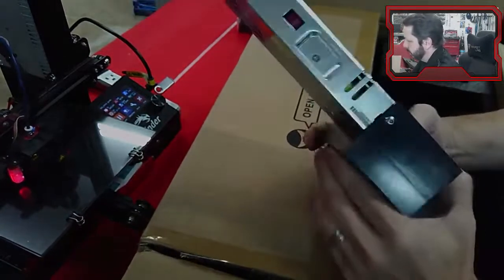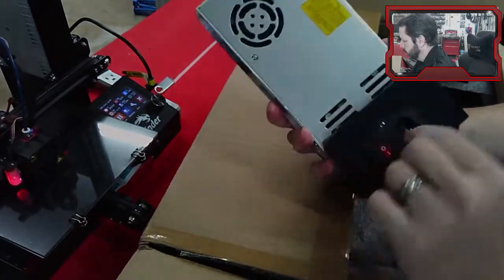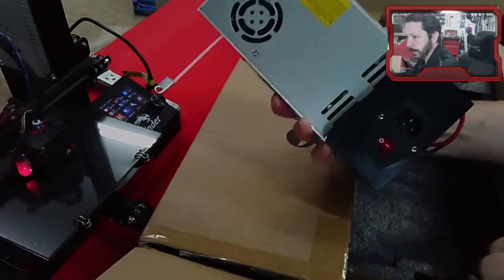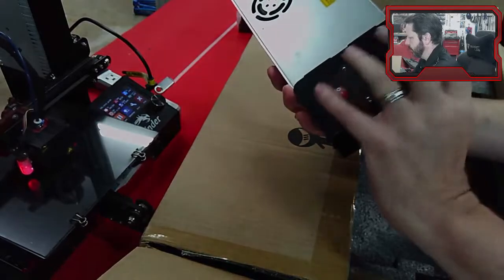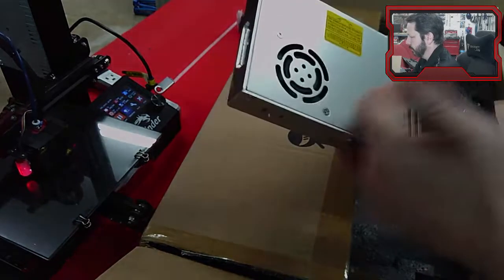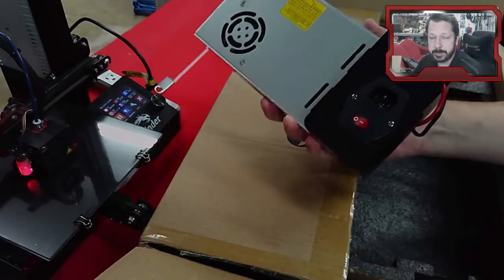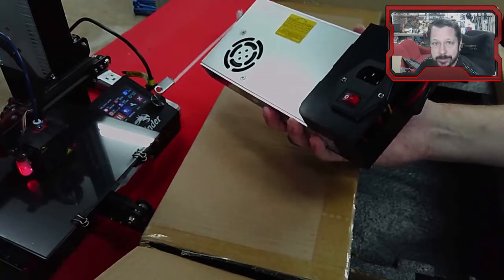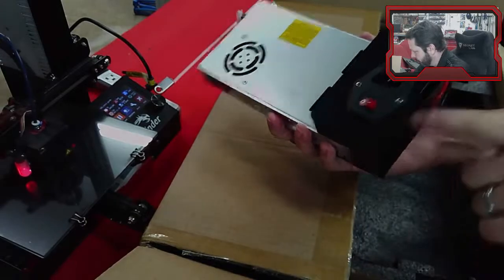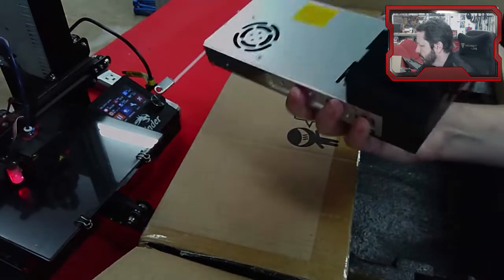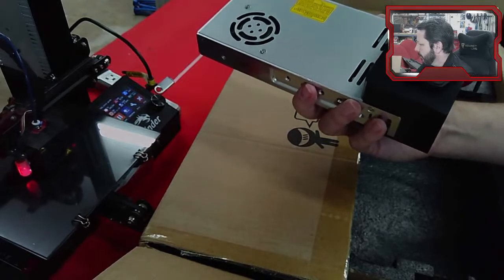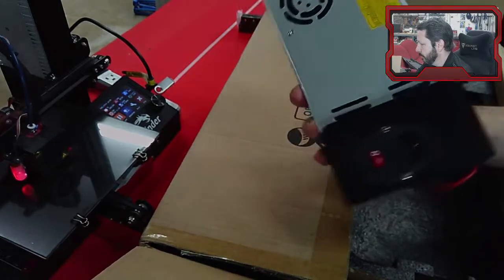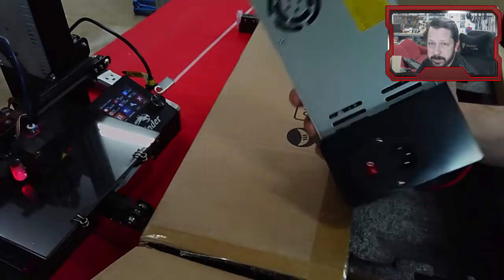The power supply. So these things, there are some kits where this is not built for you. You have to wire it up. And they don't have this shield on them. Some of the first kits that I built were just like a PC power supply that you wired the mains power directly to. So if yours is like that, then be very careful with that, because it's got 120 volts going, you know, just right across in here. Now these, they've enclosed everything, and it's better than it used to be. But if you do have an older kit, or a kit where you're wiring the mains voltage into here, then you do want to be careful on those.